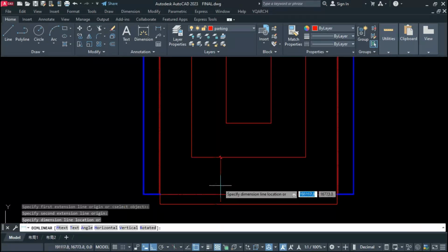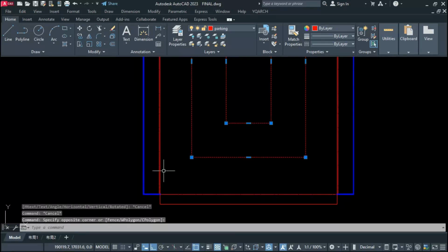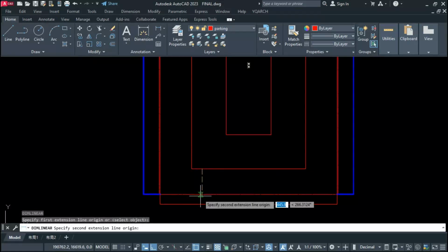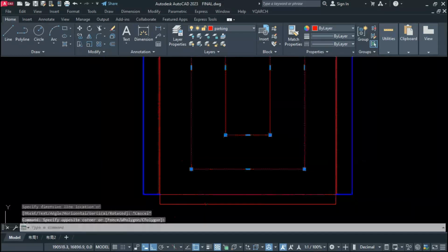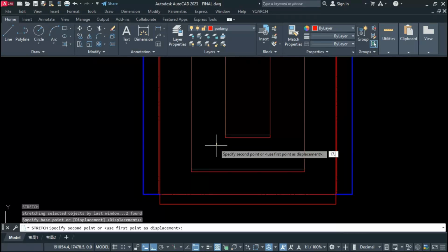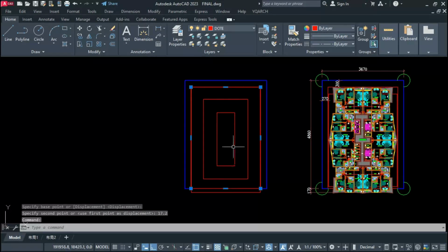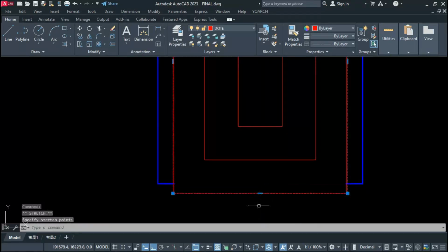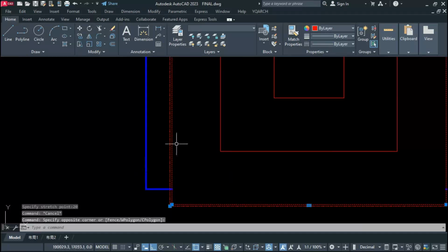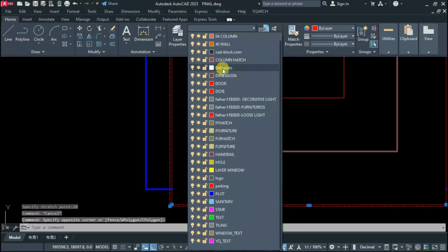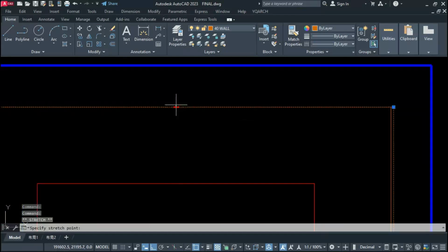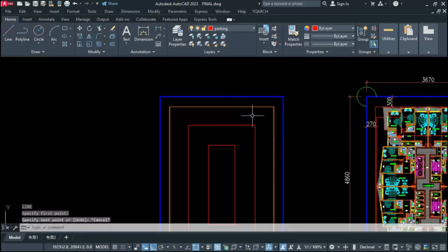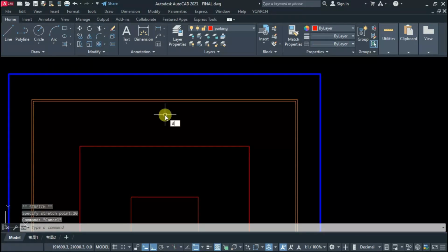In this case, what you have to do, just simply stretch this full part down. Okay. Let this be 200 centimeter. Minimum we need 550 for car parking spacing. Let this be 17.2 more. Okay. Now we are getting here 600 centimeter. Okay. This is our building line. Building line will start from ground floor. Now this is our wall. Let this wall here and let this part here also 20 centimeter. This is our wall. If you take rectangle, we are getting here. If you take 20 centimeter down.